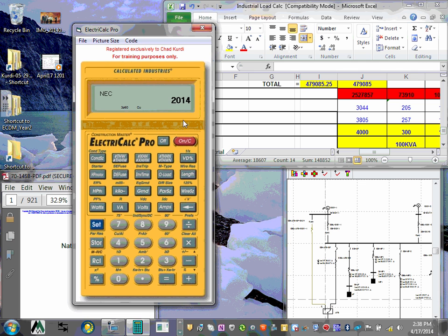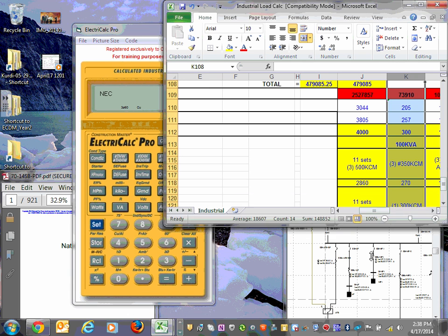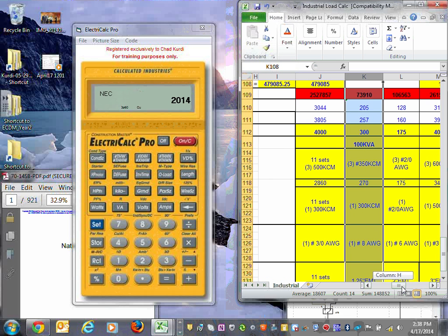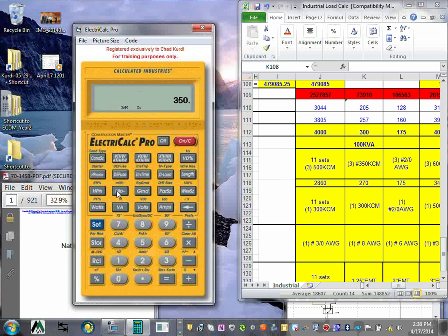THHN, right? Do you guys remember the sizing of, see, maybe I guarantee you, okay, so what was the size? 350, 300, and number 8, right? THHN all. Okay, you guys have used that calculator. So let's go 350. Here's my 350. Here's my K, wire size, 3 conductors, THHN. Okay, here you go. And what's the other one? Is 300, right? Here's my 300. K. Where's my K? Wire size. And how many of them? 1 and THHN. There you go.